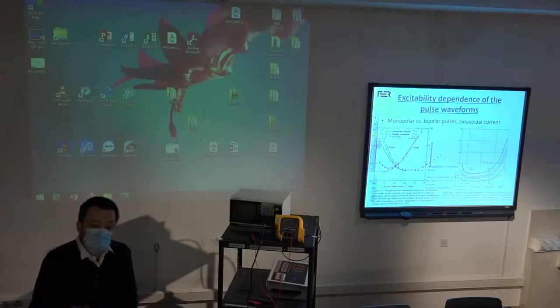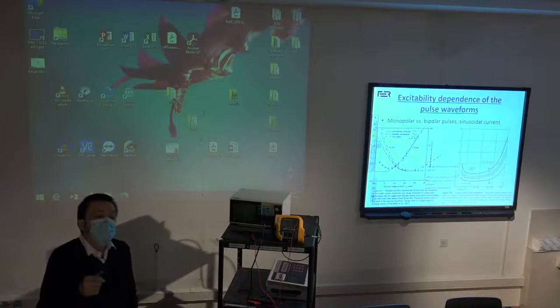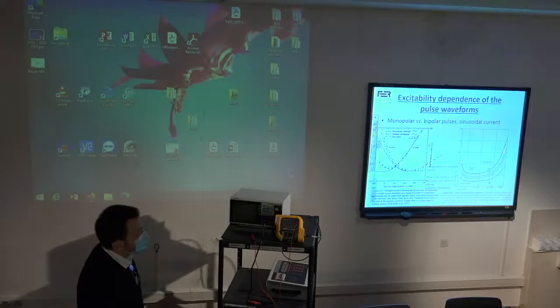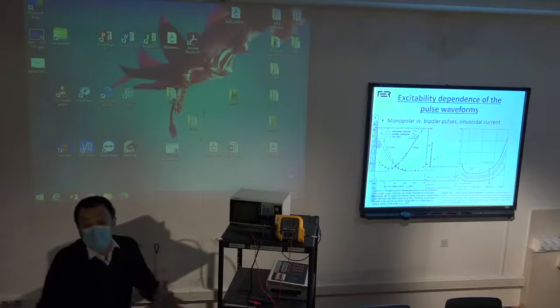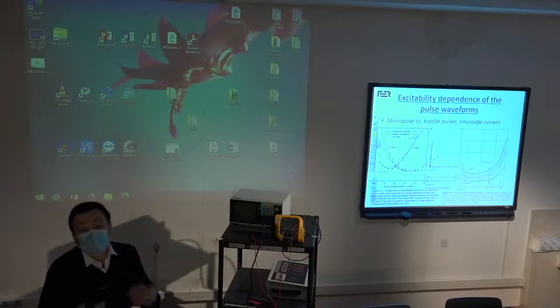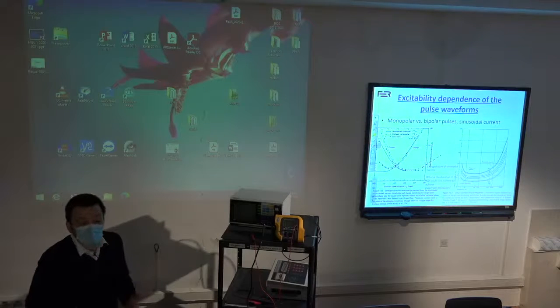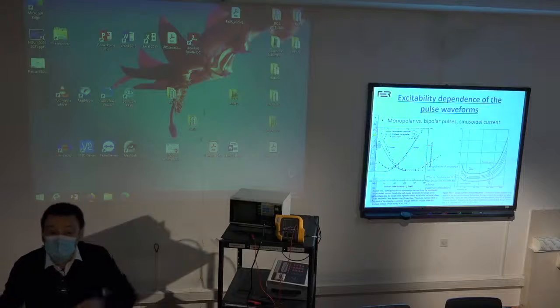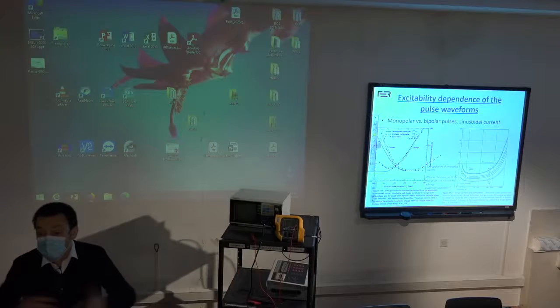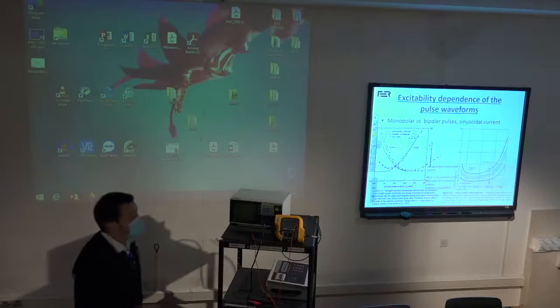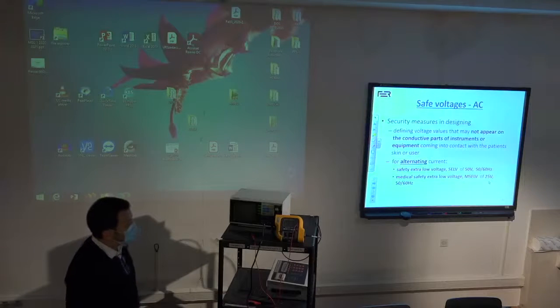So 50 Hertz, which is our mains, is among the most dangerous frequencies, because at higher frequencies you need much higher current to cause the same kind of sensation or damage to the tissue. But of course, nobody is going to change the mains to a higher or lower frequency, because the infrastructure is too large, so we can just forget it. We just have to be aware of this.